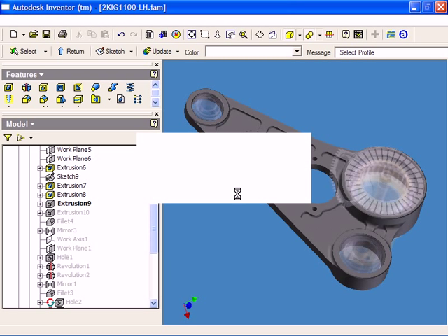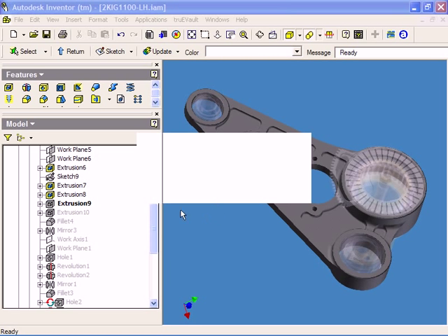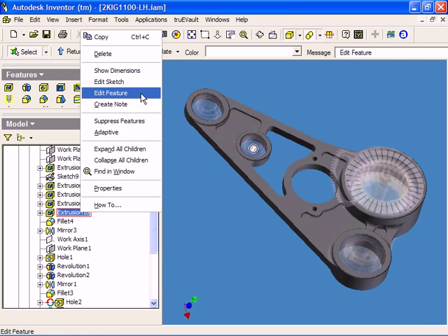As the first pocket is changed, we are prompted to check out the part as well. If we chose no at this point, Inventor will ignore any changes we made, but let's choose yes and watch how it will allow for our changes. As the change completes, we can now see the pocket is all the way through the part.